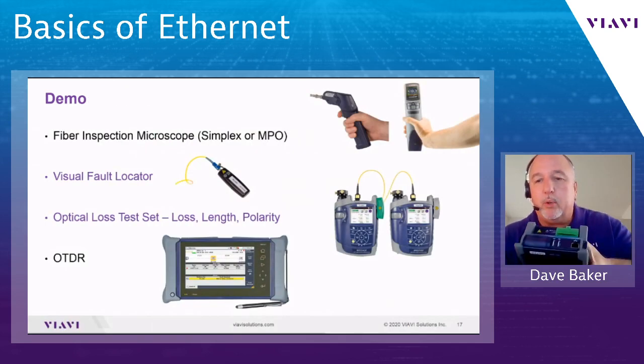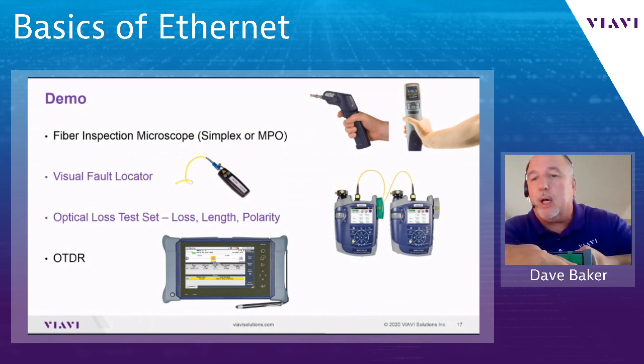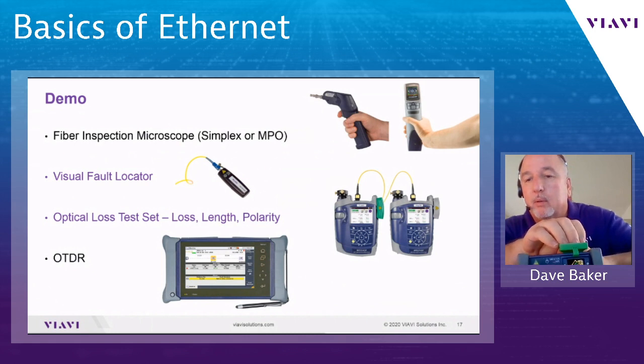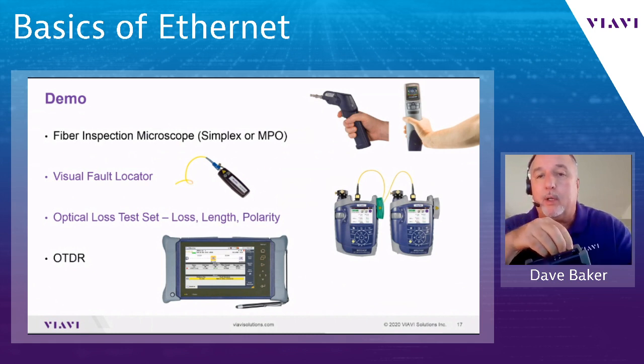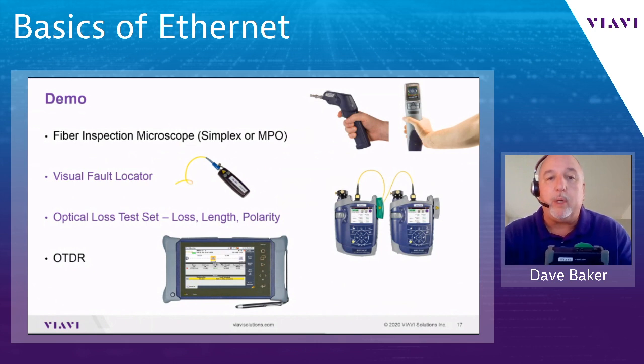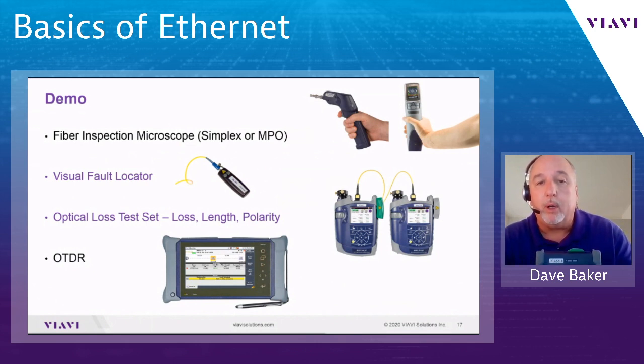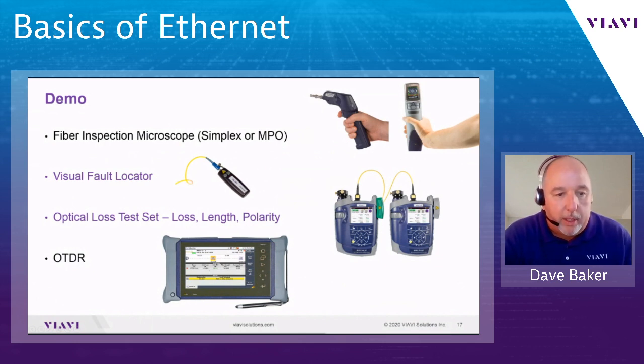Yep, so this is an OTDR. This is our T-Bird 2000. It has a connector on the top with an SC under it, with which I can connect up to a fiber under test. Not only will this measure the length and the loss on the fiber, but it measures the length and loss for individual events. So every connector, every splice, and if there's a bend on the fiber, it's going to identify all of them. Let me demonstrate that to you here.